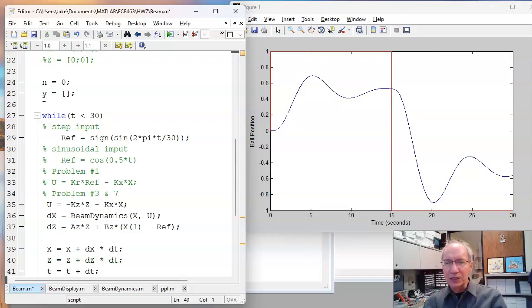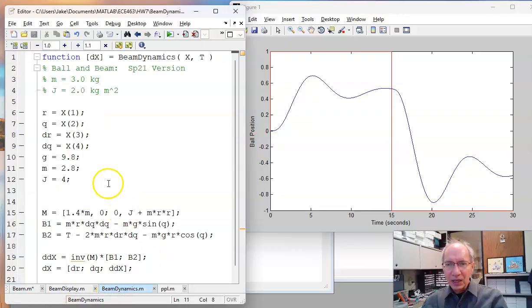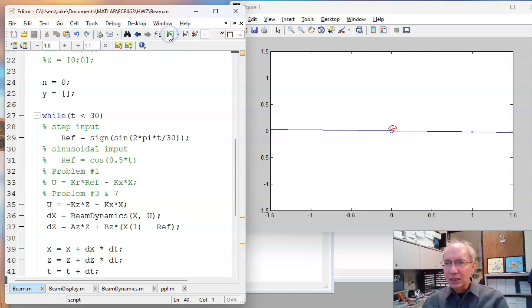Integrate the servo compensator. And now what it should do is track. If I take my nominal case, when this is 3 kilograms, it should track a constant set point just fine. That's not all that impressive because the previous control law, full state feedback, also tracked a constant set point in the nominal case. So far, I'm not all that impressed.